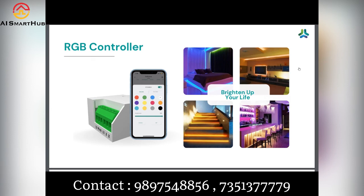RGB controller. We will move forward with the RGB controller, also known as a mood controller. An RGB controller is used to control an RGB strip. We can set the required color and the brightness of the RGB. You can even create customized color patterns. We can control it using our Smart Node application, Alexa or Google Home. We also have an extra accessory in the form of an RGB booster to increase the length of the RGB strip. We recommend connecting an RGB booster every 5 meters in between the strip.